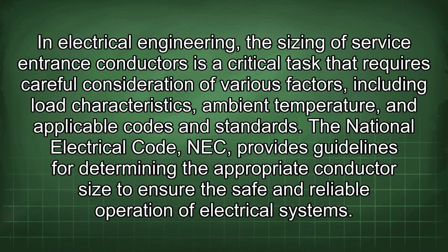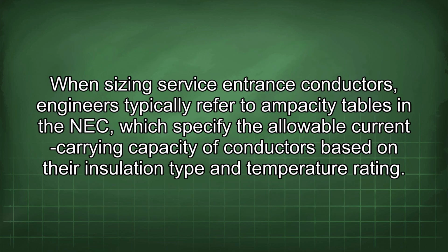In electrical engineering, the sizing of service entrance conductors is a critical task that requires careful consideration of various factors, including load characteristics, ambient temperature, and applicable codes and standards. The National Electrical Code, NEC, provides guidelines for determining the appropriate conductor size to ensure the safe and reliable operation of electrical systems. When sizing service entrance conductors, engineers typically refer to ampacity tables in the NEC, which specify the allowable current carrying capacity of conductors based on their insulation type and temperature rating.